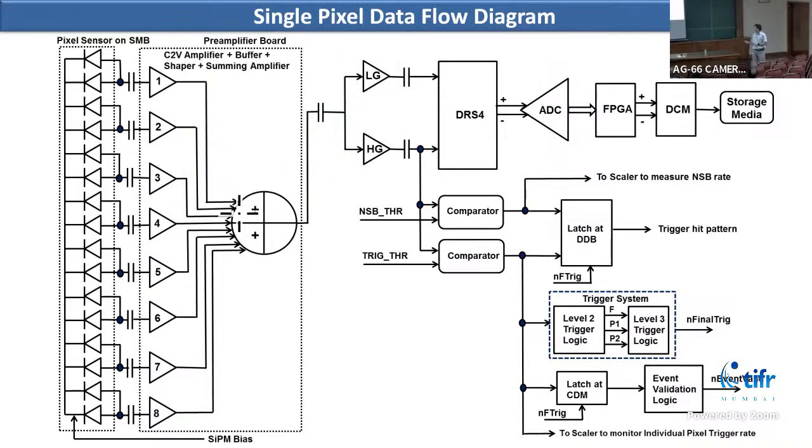Basically, it is to accurately digitize the small signals with good signal to noise ratio. Otherwise, we would have to use an ADC with a large number of bits.